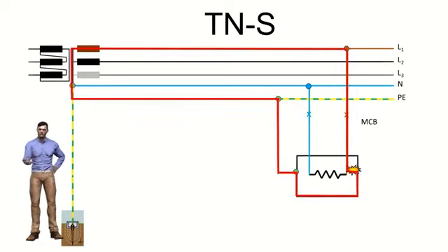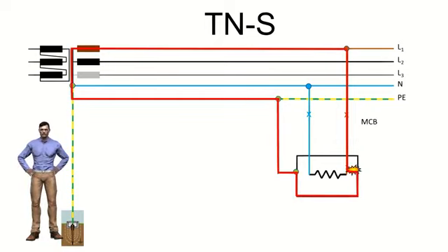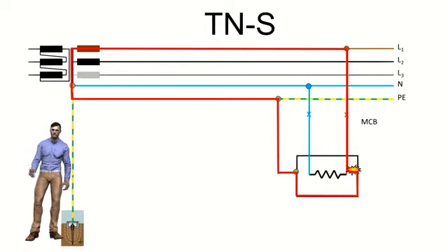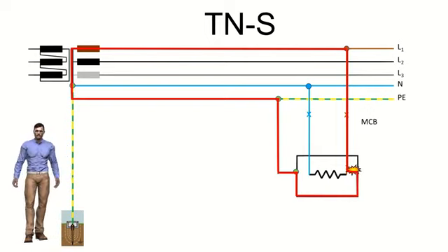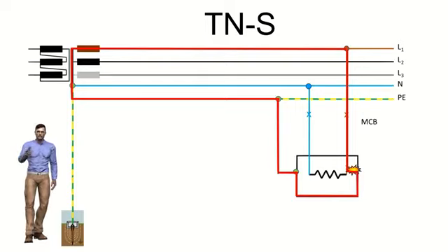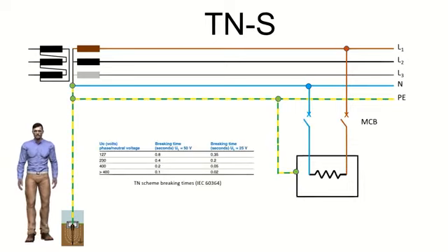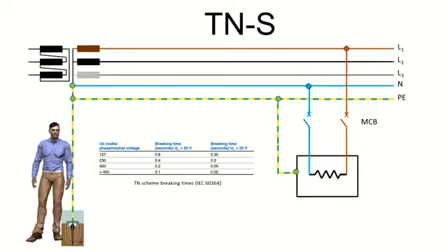In the event of an indirect contact in the receiving installation, for example, due to an insulation problem of an active cable inside a machine, a contact occurs between a phase and the ground of the receiving installation. In this situation, the fault loop we have is made up of the phase conductors and the protective conductor PE, or PEN, and the transformer winding, so its impedance is very small, giving rise to the appearance of a high short-circuit current that does not involve the earth electrode of the supply. In this case the protection against indirect contacts is carried out by means of the appropriate choice of the activation curve of the protections against overcurrents and short circuits, that is to say, circuit breakers and fuses.